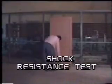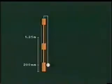The last lab test is the shock resistance test. A leather ball of 20 centimeter dia filled with sand weighing 5 kilograms is made to swing and hit against the door 15 times. The general condition should be checked after every 5 blows. There should be no visible damage after 15 blows. The ball should be lifted up to a height of 1.25 meters above the point of impact, which should be 200 millimeters above the bottom of the door.